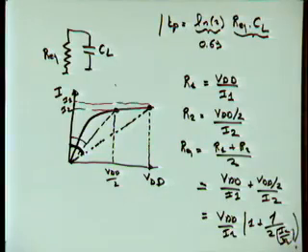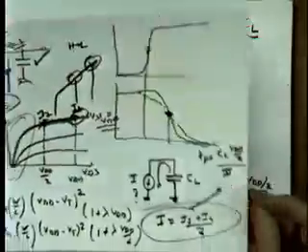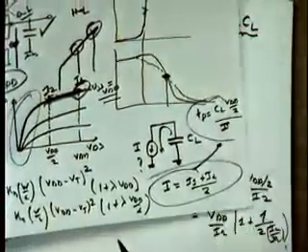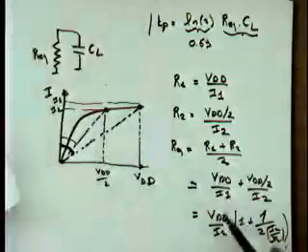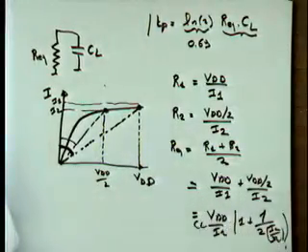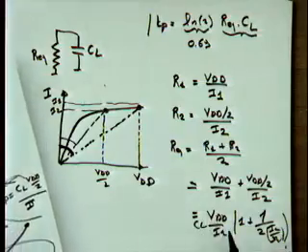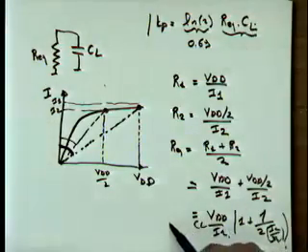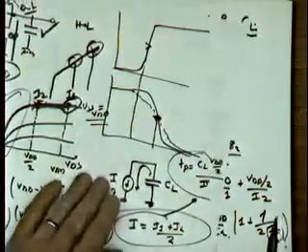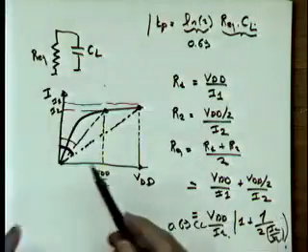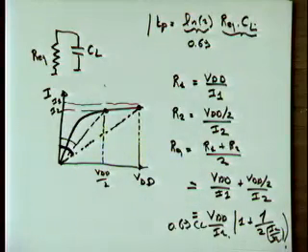Plug in the equations and do the whole analysis, and you will see that you get an equation pretty close to the one I got from here. They're not that different. So I have the R equivalent, I multiply it with CL and with 0.69, and you compare it with this equation here, and you see they're very close. They're not going to be perfectly the same, because we used a different way of averaging. So as a result, there will be a small difference.